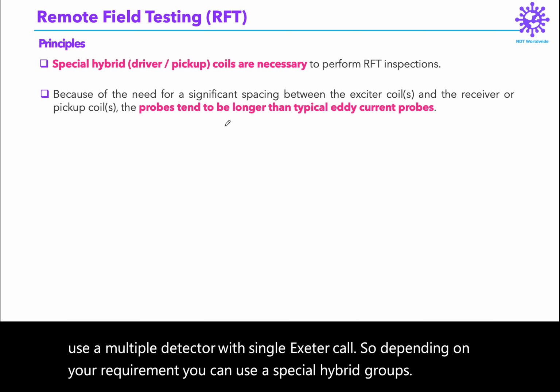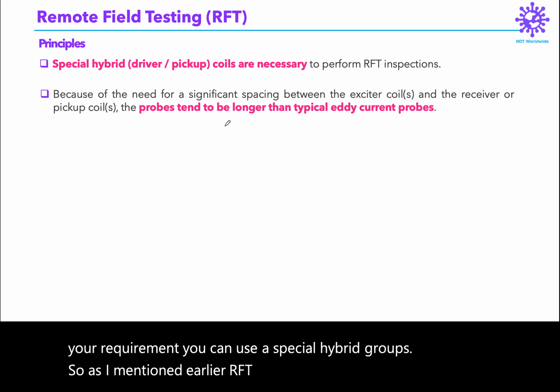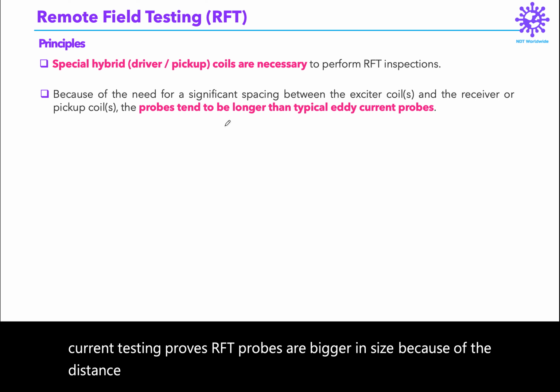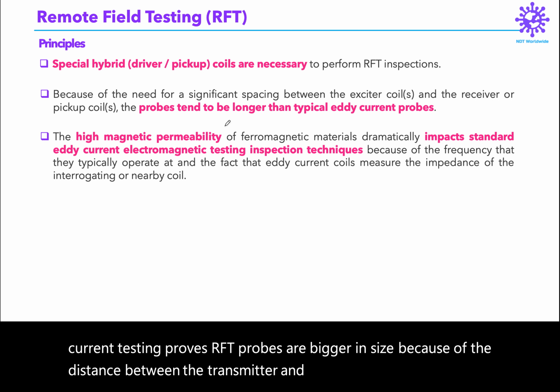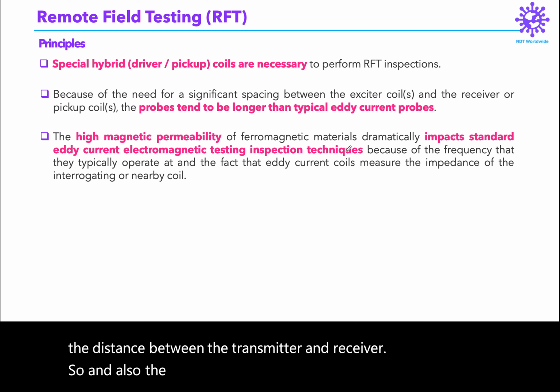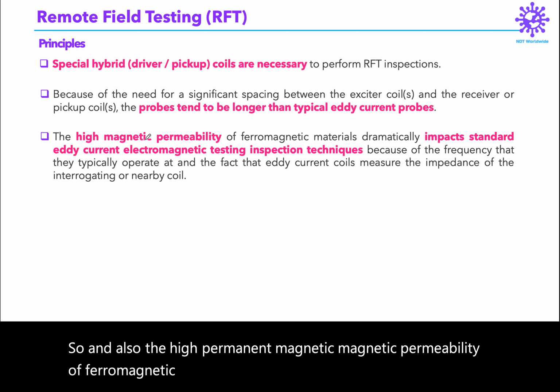As I mentioned earlier, RFT probes, compared with eddy current testing probes, are bigger in size because of the distance between the transmitter and receiver. Also, the high magnetic permeability of ferromagnetic material drastically impacts standard eddy current testing.